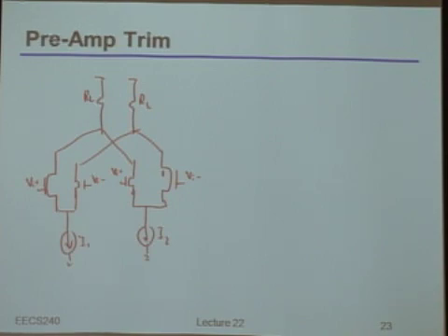Right? So again, the whole idea here is that simply by moving current between I1 and I2, I can intentionally tune the level of asymmetry in my input devices, and by doing that, tune the relative input referred offset. But I can still do that in a way that allows me to always use that current to actually get a GM out of the structure.